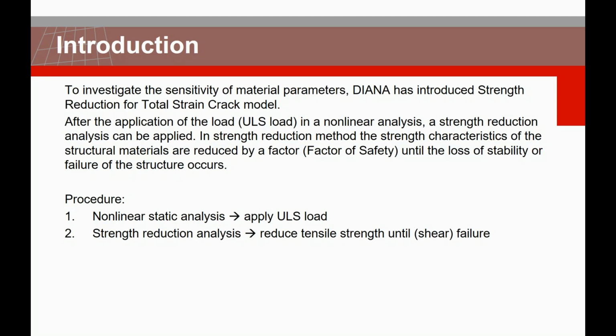So what we do, I will explain it later in the live demo. We will actually do a sort of investigation on the sensitivity of, in this case, the tensile strength. And we use the new feature, strength reduction for total strain crack models, for this. To do that, we first have to apply a certain load, let's call it the ULS load, in a nonlinear analysis. And subsequently, then a strength reduction analysis can be applied.